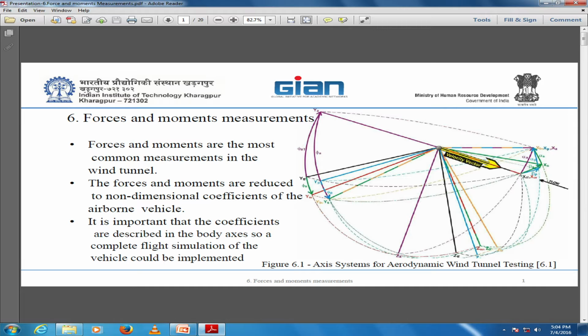Do they have to be calibrated often? No. Usually, string balances are not calibrated often. But with this automatic machine, you would like to calibrate retroactively. If you have a series of experiments, then you probably would like to gain more accuracy, so you retro-calibrate your data according to the history of the test.